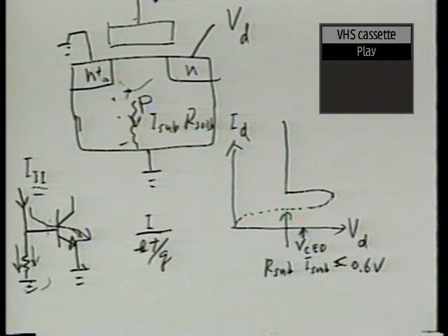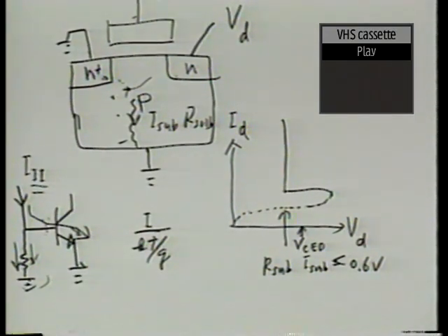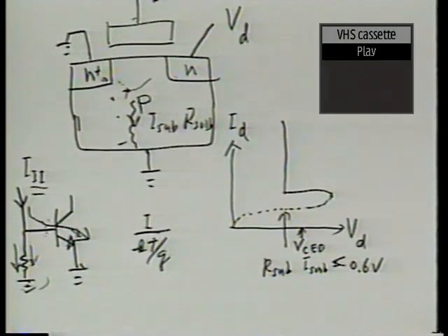How about some of you try to answer that? Why is it? The hint is to think about the same situation as here. In other words, when you ground, is that really ground? Now think about the cross-section of the bipolar transistor. When you ground the bipolar transistor base, do you truly ground it? Here already the resistance of the base is causing this problem. We cannot truly ground the base, right? Now think about the resistance value of the base of that transistor.